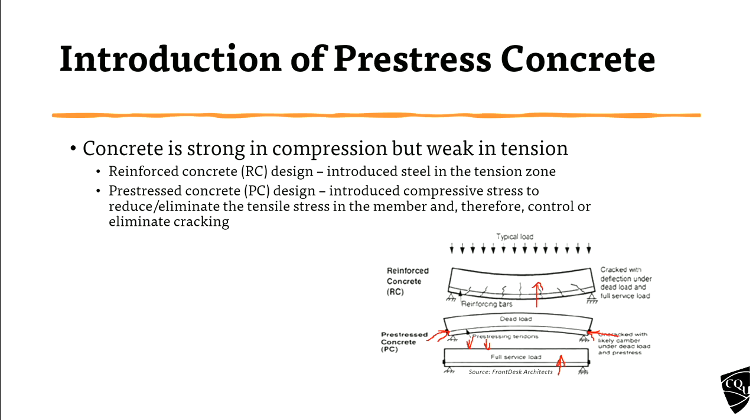Okay, because in the RC beam normally we have a flat beam and we apply the load, it will go downward. But in the pre-stress one, before we apply the load, it's bent upward, so upward deflection. Then when you apply the load, it will come down, become flat, then go down.